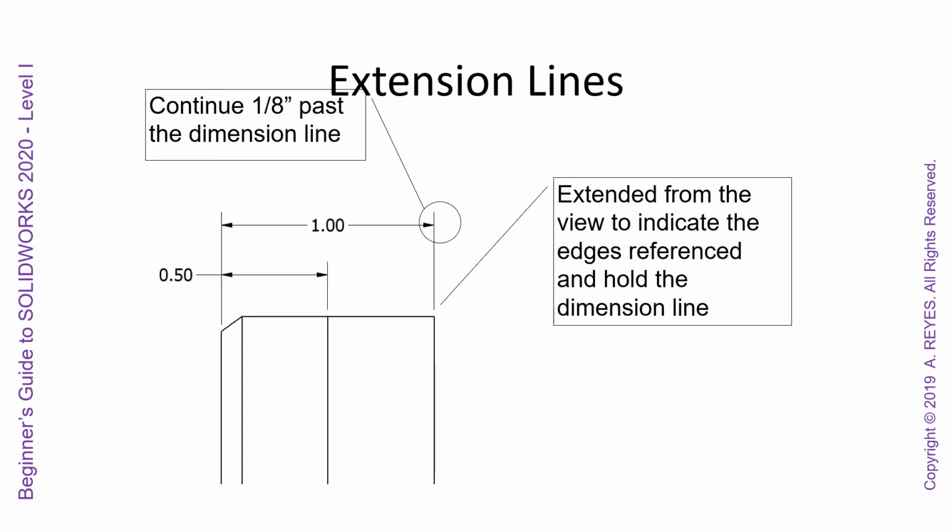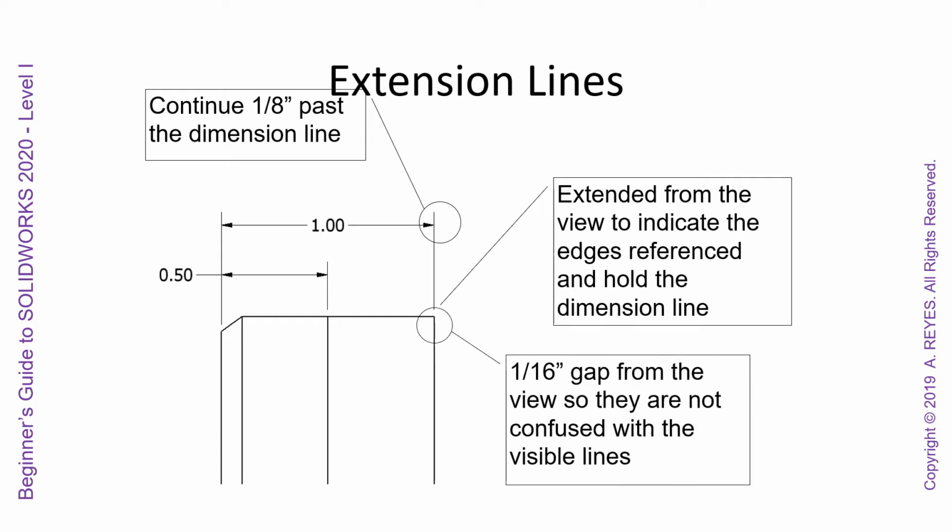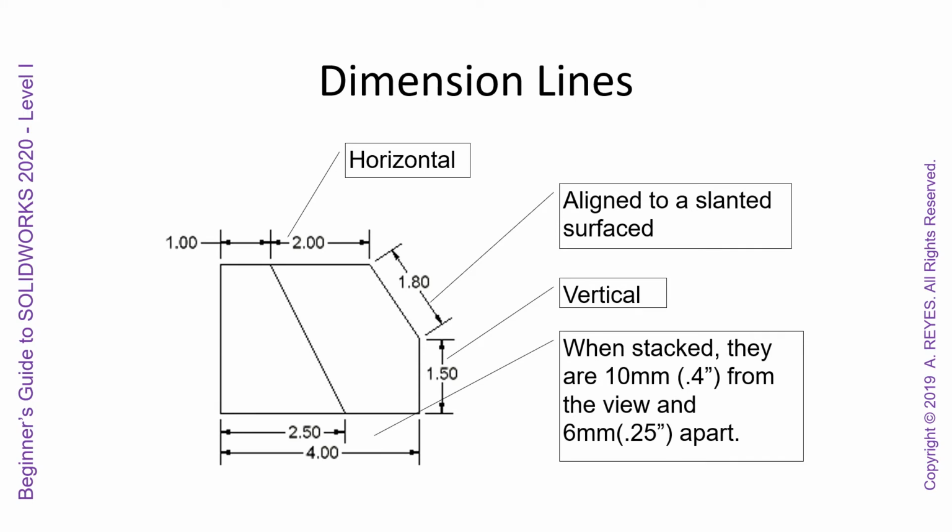They are extended from the view to indicate the edges referenced and hold the dimension line. You also want it separated so that they don't look like they are part of the actual part. Right there, the 1/16 inch gap, so they're not confused with visible lines.